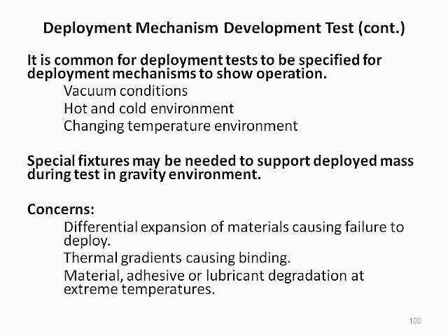Some typical concerns that are investigated during development testing are differential expansion of materials causing a failure to deploy, thermal gradients within the mechanism causing binding during deployment, and thermal degradation of materials, adhesives, or lubricants at extreme hot or cold temperatures.